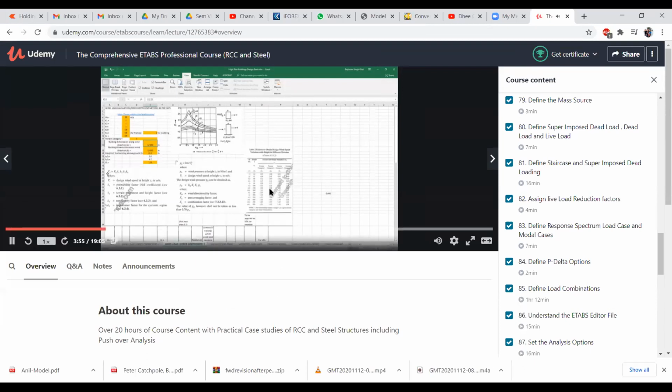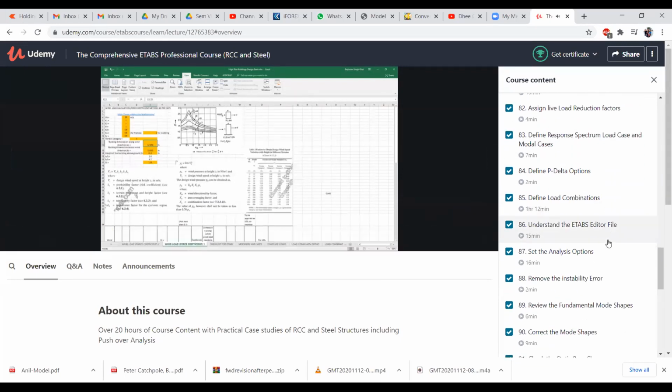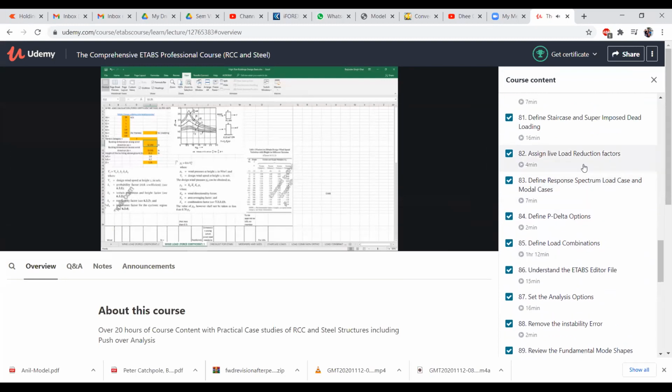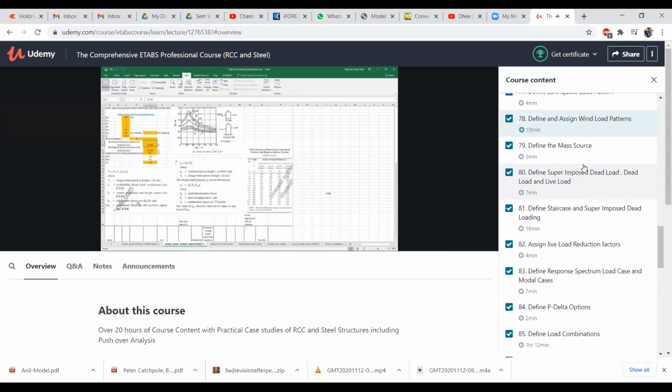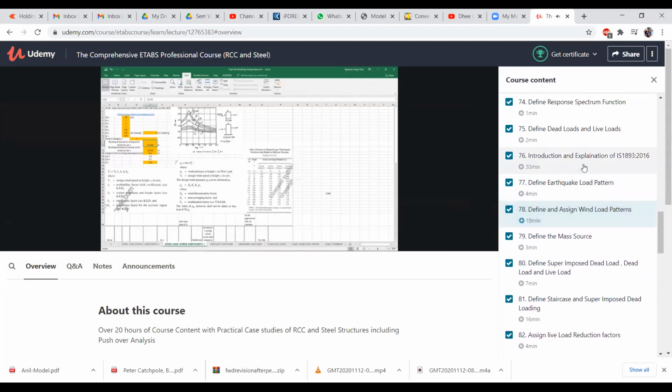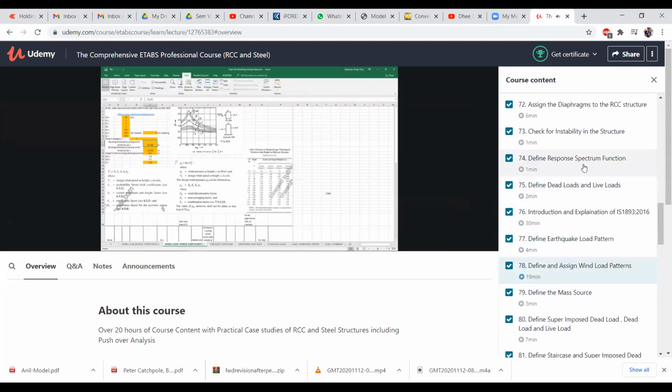that is Vz. How can we calculate design wind speed Vz? We can do that by multiplying Vb, that is basic wind speed, into K1 into K2 into K3 into K4. K1 is a probability factor, which is 1 for our building. K2 is the terrain roughness and height factor, which shall vary as per this Table 2. K3 is the topography factor, that is 1 for our building, and K4 is the importance factor for the cyclonic region.